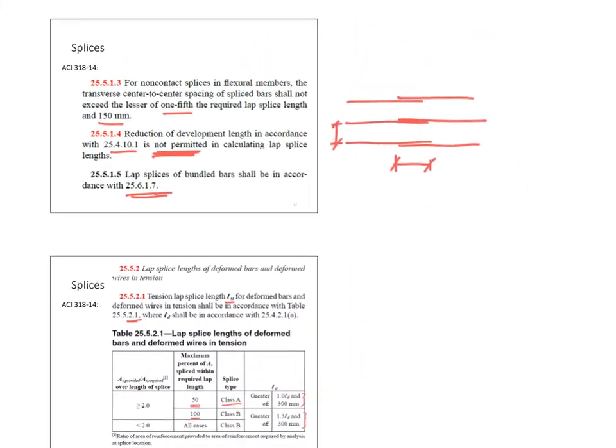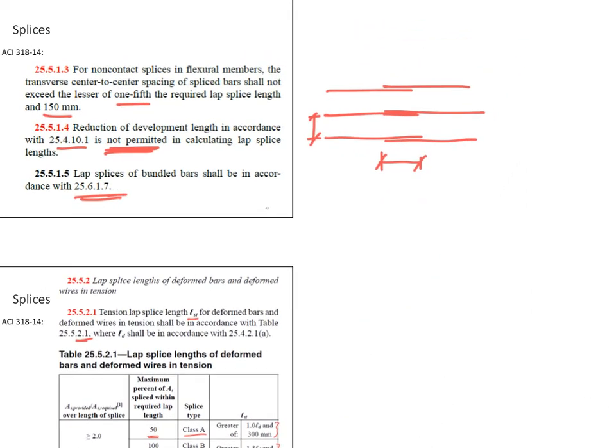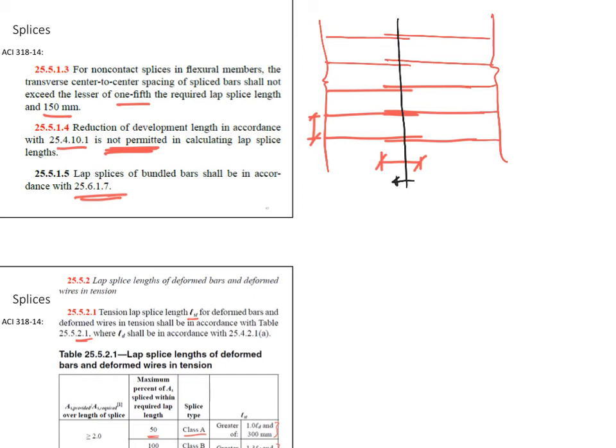It means if I get back to this picture over here and I start splicing everything within the same section. So now I'm splicing, I keep just putting the bars coming. This is a break line. This is a break line. Imagine this was like a slab or a raft, and I'm just splicing everything in the same place. Now, if I take this section, I'm cutting and looking. Think about this. How much percent of the bars are spliced? In this case, I have 100% spliced.